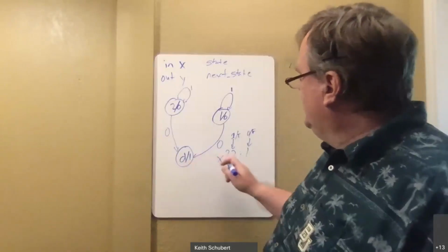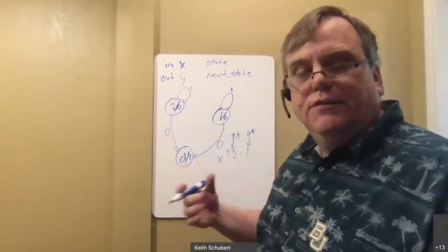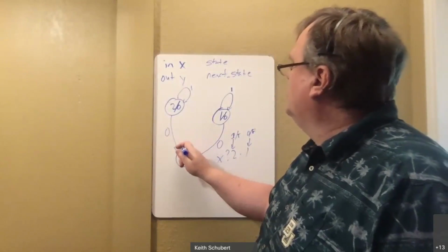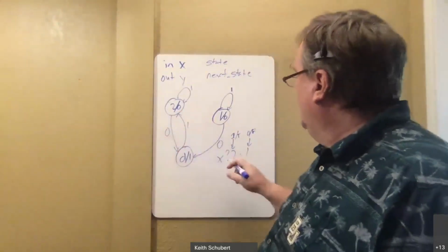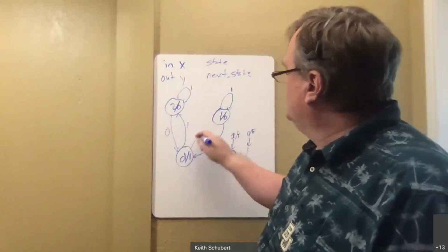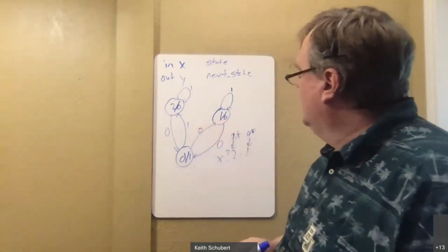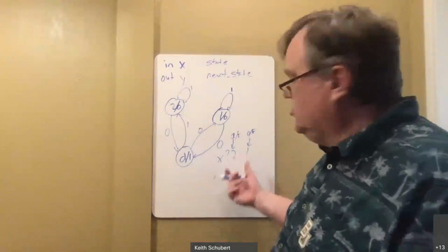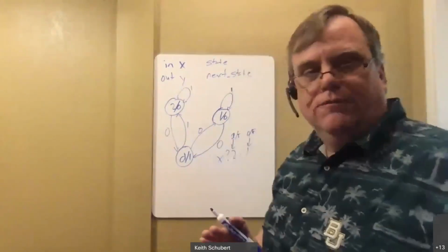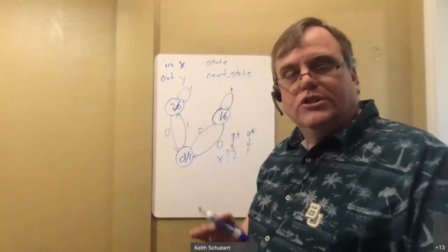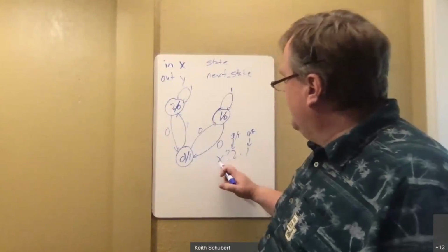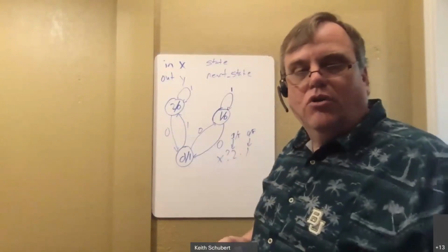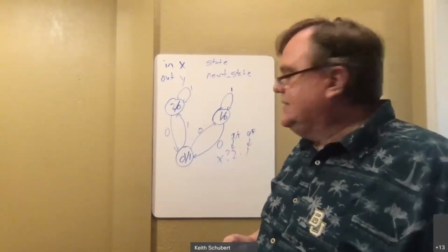So if I'm at this default case and I get a 1, I will go to state 2. And if I'm at a 0, I will go to state 1. That's all that's telling me. The question colons always look weird, but once you get used to them, they're very, very nice. So it just tells me which way I'm going based on whatever x's value. X is a 1, it does the first. X is a 0, it does the second. That's all there is to it. And next state gets that value.